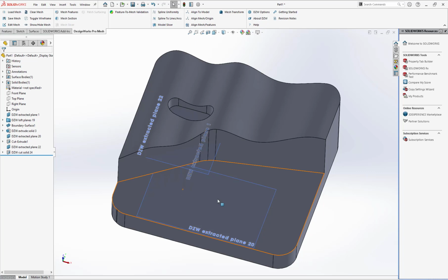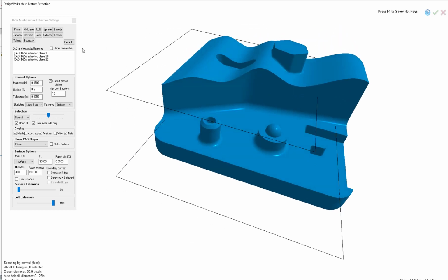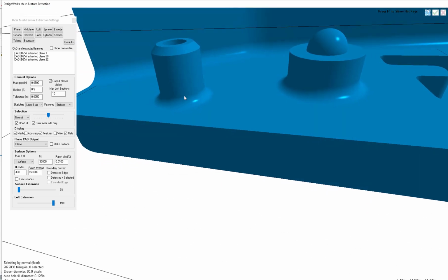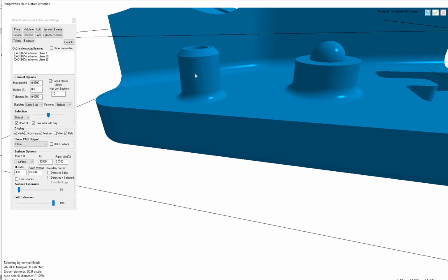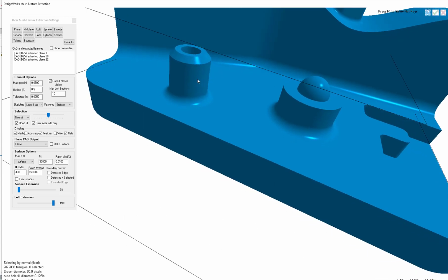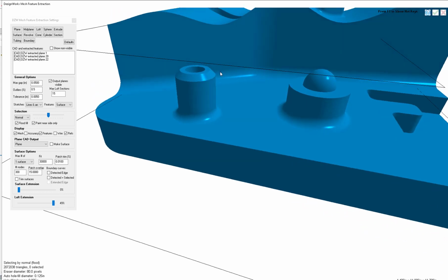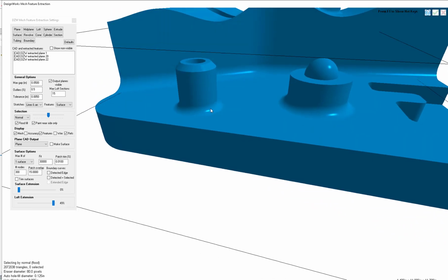Let's build a couple of these revolves down here. They have the same issue. And that's exactly why we built this. So again, here's a case. This is a double whammy. This is where if you're using some other products that aren't as intuitive as ours, you have to build a plane down here, a plane on top, then build the cylinder. Then when you got done, you'd have to edit the feature in the SOLIDWORKS tree and say up to plane, up to plane, because nobody can build features on 3 different objects.